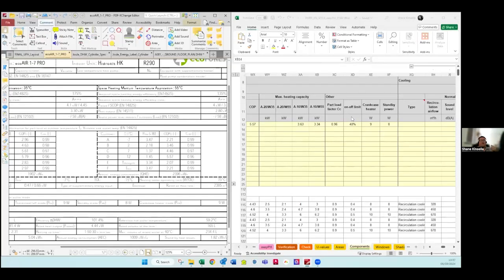Essentially what it's saying is how slow can the compressor go before it has to switch into a fixed speed mode. Most compressors, by the time they get to 30–40% of their design speed, are no longer able to wind down any further, and they have to run at that level as a minimum, in which case they have to switch on and off and go into effectively a fixed speed mode. So typically we put that value in around 40%.